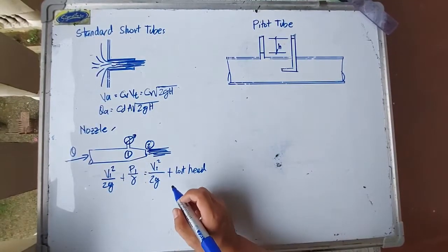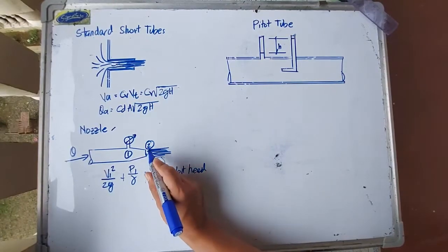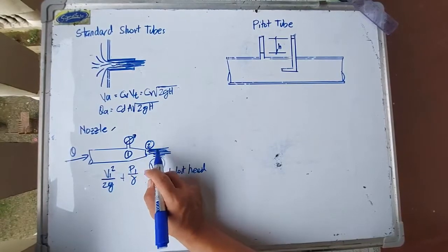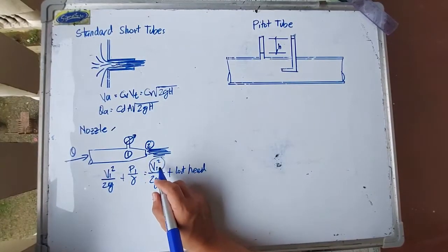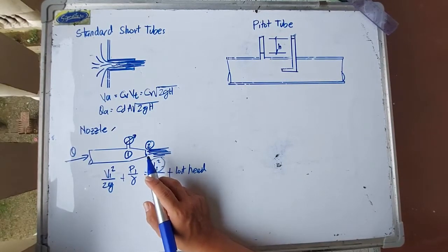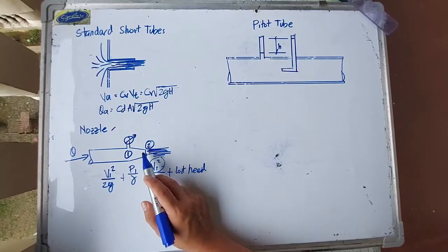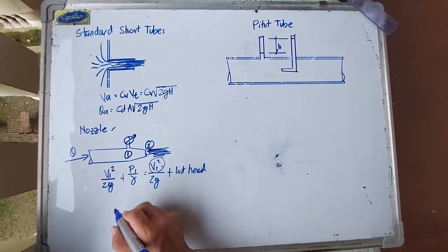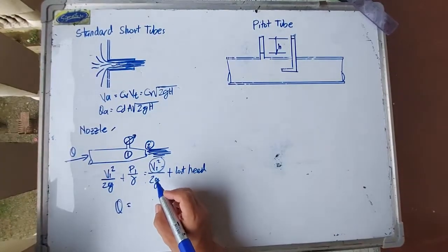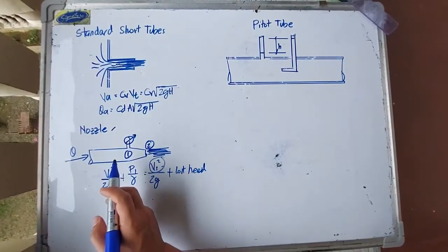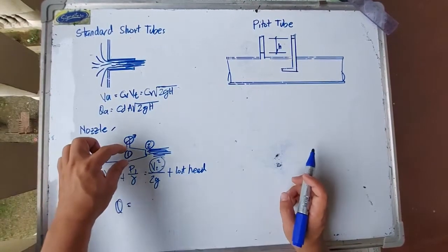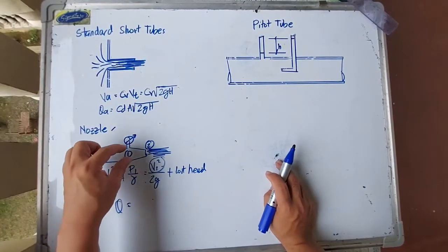And then we measure the pressure at that inlet point, and we apply the energy equation to solve for the velocity at point 2, at the outlet. The liquid will come out there. So we can measure the velocity at point 2. And if we know the cross-sectional area of the nozzle, then we can solve for the discharge. So the discharge is simply equal to the actual velocity, considering the loss of energy when the particles of the liquid travel from point 1 to point 2.